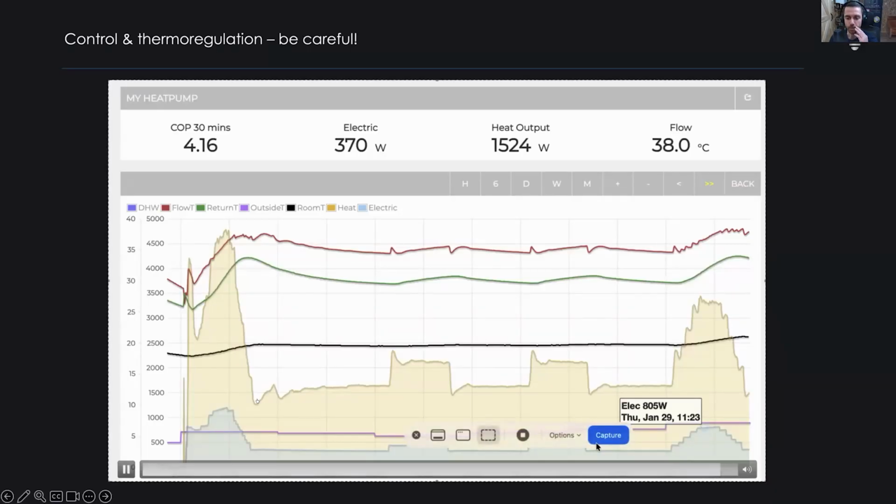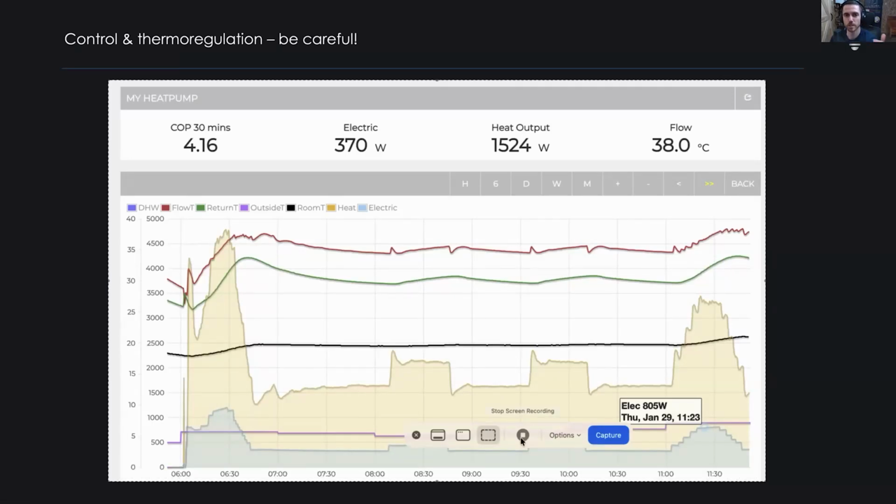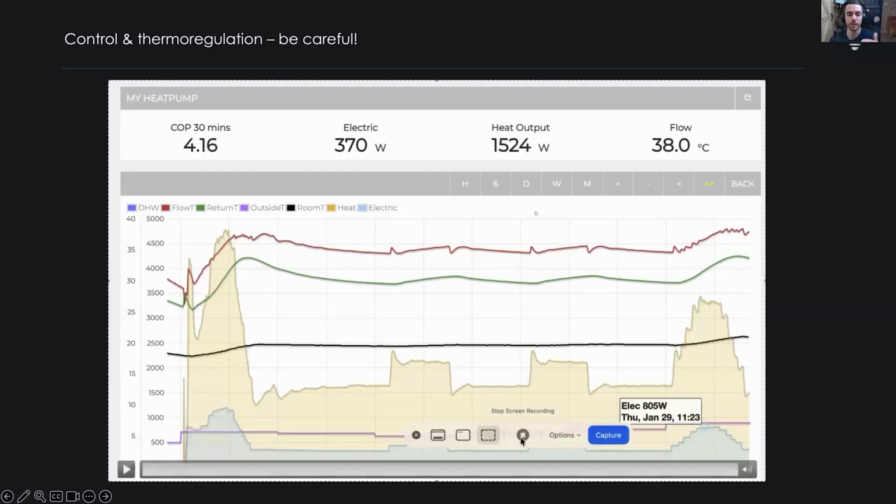So this was also strange for me, but I then talked with the guys in Bosch, and they said, yeah, you need to go inside of thermoregulation. So this is always my advice to everyone working and commissioning heat pumps. Try to be comfortable with your manufacturer, because every manufacturer is different. Everyone has some specific parameters where you can have really poor COP.